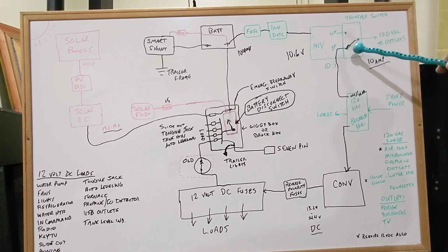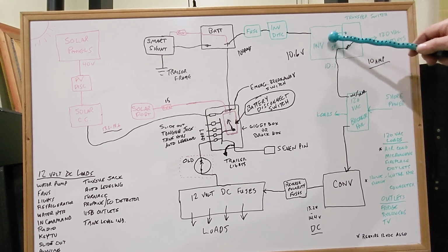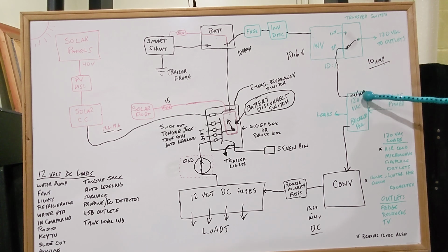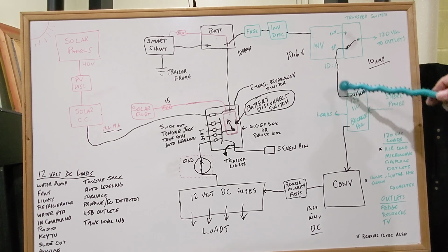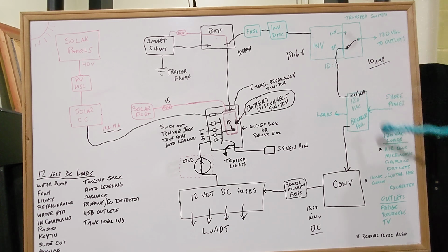So normally, when the inverter is on or off and you have shore power connected, inside your breaker panel you'll see a breaker labeled invert, INV, or solar, something like that. That's the breaker that's supplying the power through the inverter to this outlet string. It's just one of these outlet strings that I mentioned earlier.